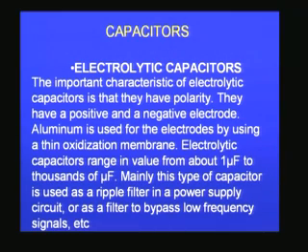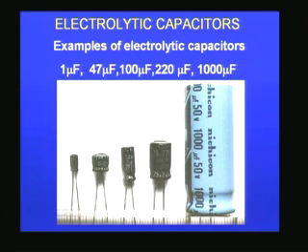will be the varying DC. So, you will have an average DC over which there will be a variation or an alternating voltage, and therefore, it is something like, for example, the ripple voltage in the case of a power supply, things like that. So, electrolytic capacitors are always used under DC conditions, but varying DC conditions, and therefore there is no harm. Still, they will only take care of the alternating voltage that is being applied.